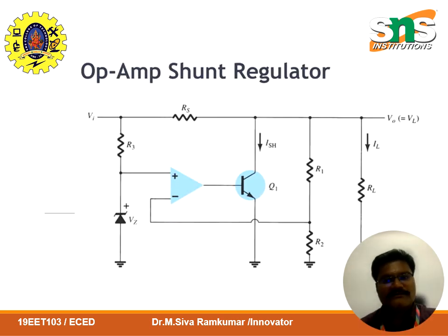An op-amp shunt regulator controls the voltage using a simple feedback setup. It uses a Zener diode to set the reference voltage. The op-amp compares this with a sample of the output. If the output rises, the op-amp drives the transistor Q1 to conduct more, diverting the current through it and lowering the output. This keeps the load voltage steady.